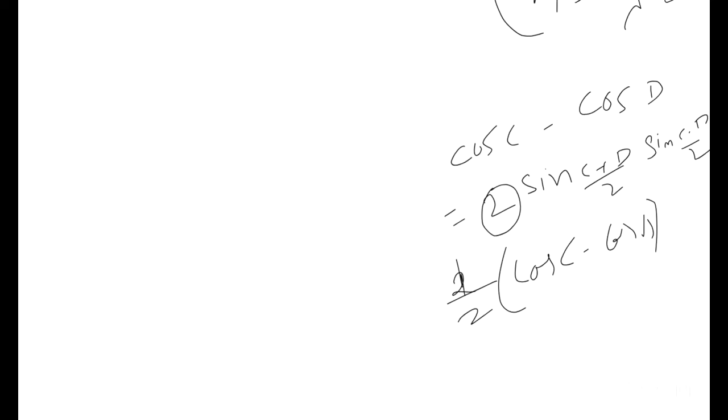Here I am taking dr by dt as the radial velocity, Vr. If dr by dt equals Vr, in place of dr by dt I am substituting Vr. After substituting, cross-check the equation. What you will get? Angular frequency equal to 2 pi fd equals 4 pi by lambda times Vr. In place of dr by dt, Vr is written.